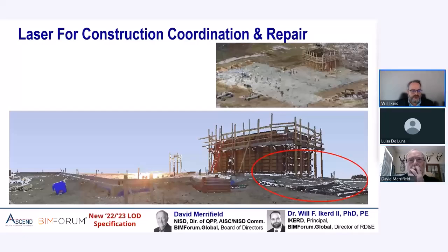Incredible story, incredible project. One of the takeaways I have here is this would be an area where the anchor rods would be specified to LOD 350 modeling, and the laser scan provider would be given tolerances that those anchor rods needed to be within. These are examples of model extraction. So that is an as-built anchor rod. So LOD 500 as-building with a geometry based on 350.